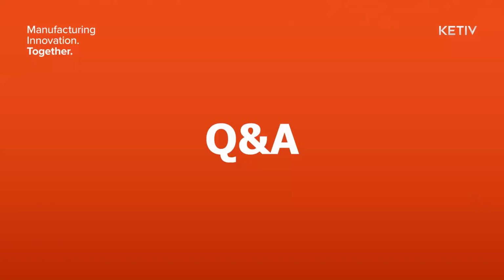Yep, and you can vault all this stuff too. If you use Vault in Factory, there is some setup to be had, because you have to put your asset library somewhere. You just want to make Vault aware that you're using Factory, and this is where my Factory assets are going to go. It's pretty simple, but make sure that you do it, or else you'll run into some issues. A lot of this will be in the help file specifically for the utilities, and there is a separate pull down for help and Factory.